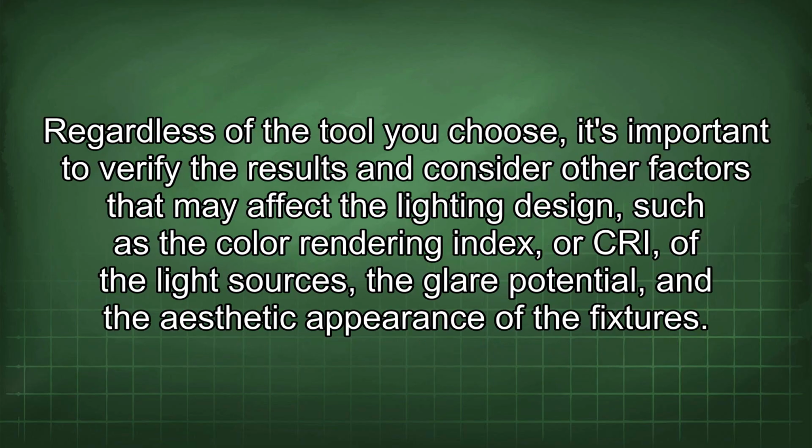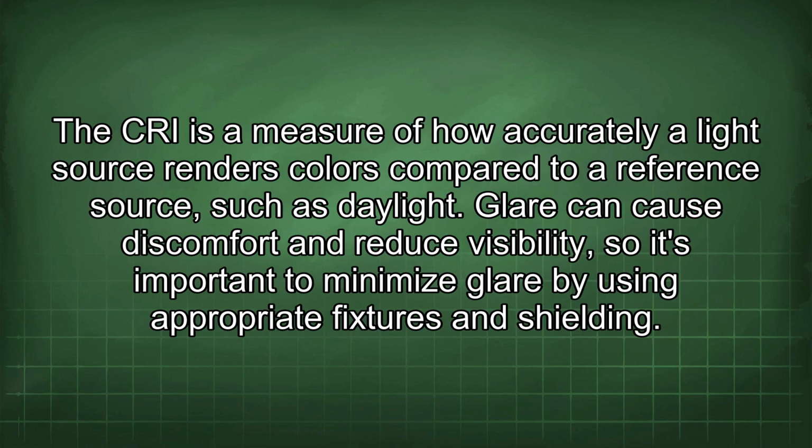Regardless of the tool you choose, it's important to verify the results and consider other factors that may affect the lighting design, such as the color rendering index, or CRI, of the light sources, the glare potential, and the aesthetic appearance of the fixtures. The CRI is a measure of how accurately a light source renders colors compared to a reference source, such as daylight.